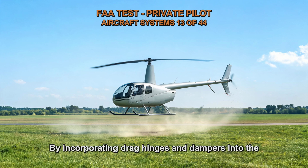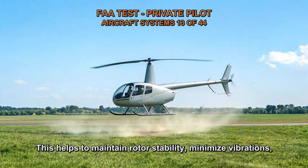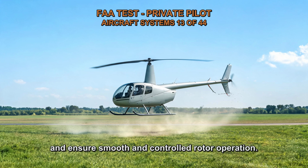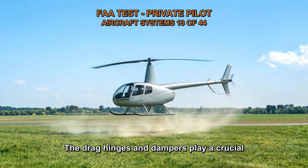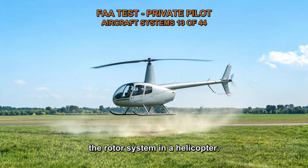By incorporating drag hinges and dampers into the rotor system, the oscillating motion of the blades caused by the Coriolis effect is dampened. This helps to maintain rotor stability, minimize vibrations, and ensure smooth and controlled rotor operation. The drag hinges and dampers play a crucial role in maintaining the integrity and performance of the rotor system in a helicopter.